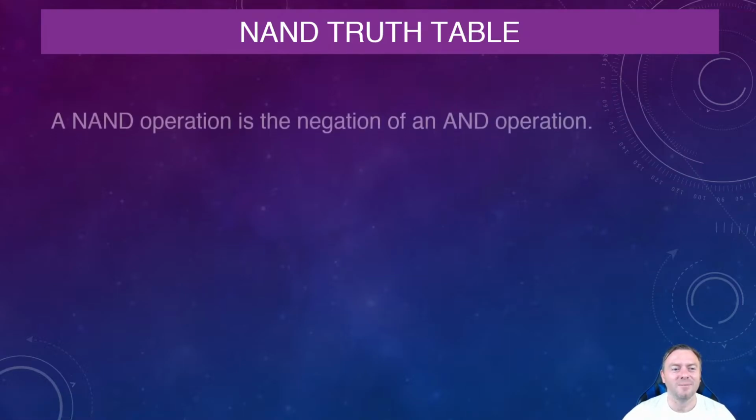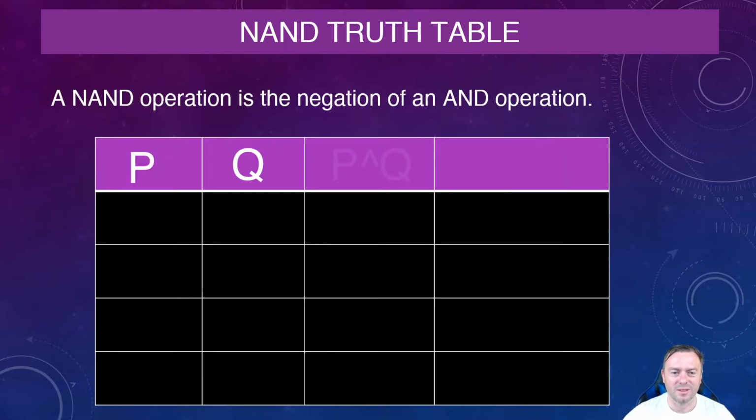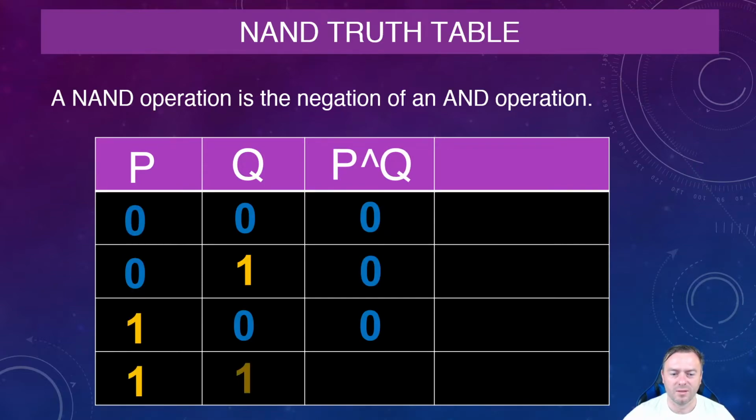Okay. Right, so then we've also got the NOT versions of those three gates. So a NAND gate also looks like this. So we've got P, Q, right? Same as what we did before. So this is the unique case. When we do the NAND of that, basically we flip all these circuits. So zeros become ones and ones become zero.